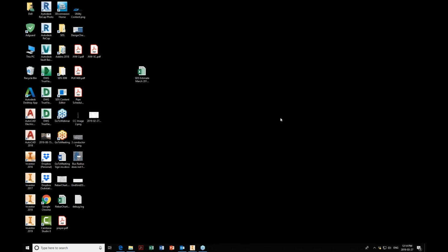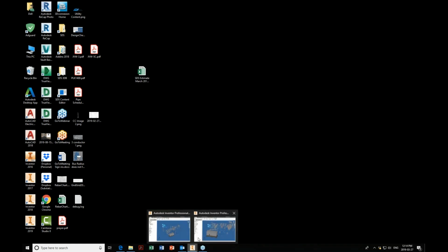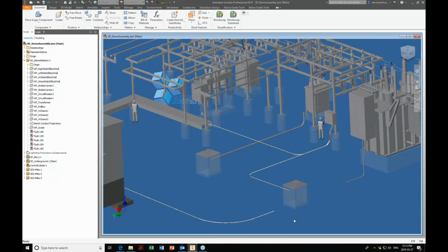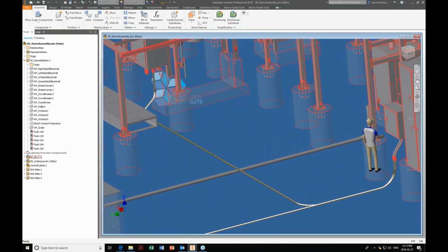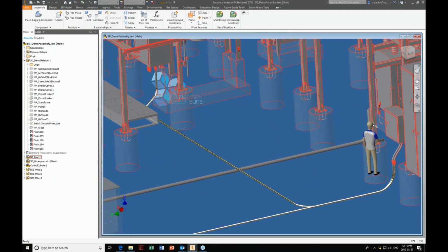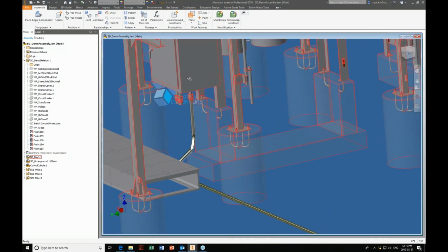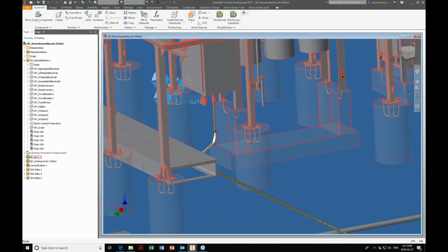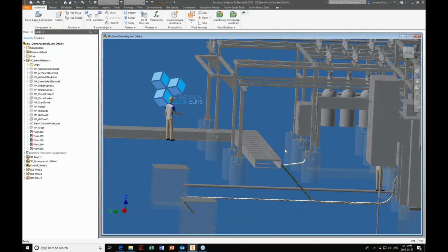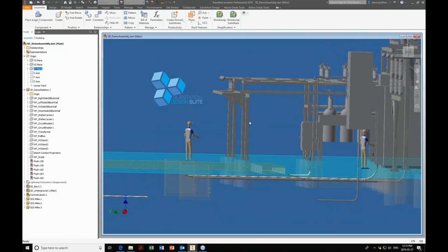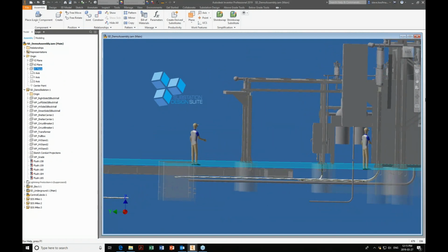So I just wanted to show what we had done ahead of time to prepare for creating these. As you can see again in here, we are bringing down conduit. We're going to bring it from an above grade location and bring it into a above grade down here, and we're going to draw a path, and it's going to be under our grade. So if you follow a substation modeling strategy, we have the XY plane here, and that's top of concrete typically.